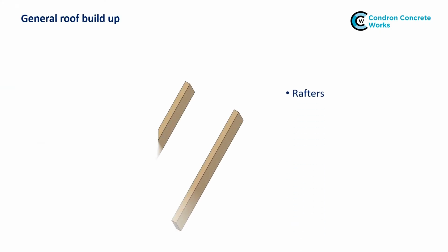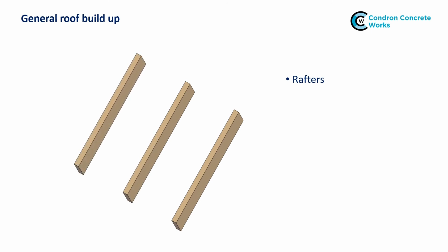Therefore, adding extra ventilation when the underlay is capable of controlling condensation may not be desirable. So what else can we do to overcome the problem of excessive condensation in the batten cavity? An alternative option is to install counterbattens over the underlay and vent the batten cavity.